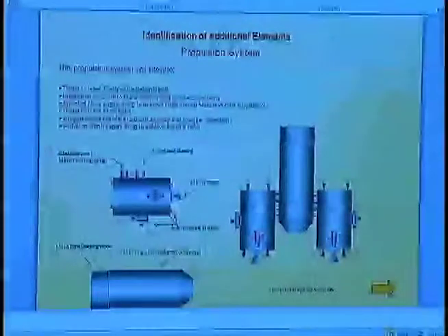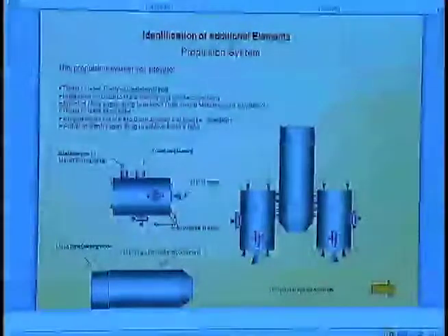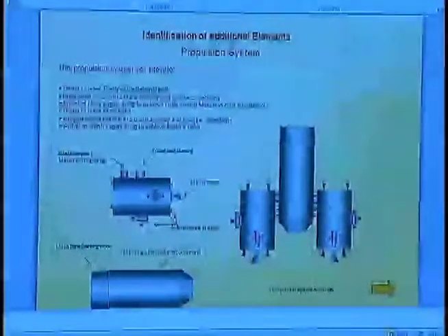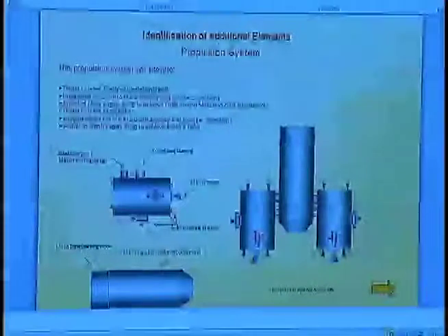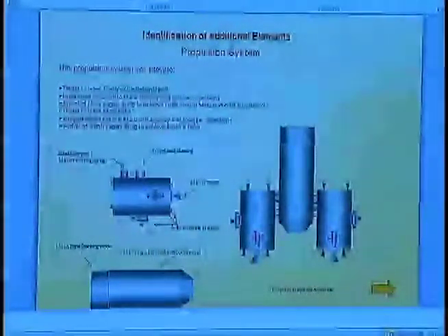Now here's the propulsion system. Let's expand on this. This system is formed by a module which contains propellant to feed two rocket systems. Each of these rocket systems has a main engine, secondary engines, and route correction engines. Inside is a propellant which is to be used by the secondary and correction engines. The main module has the computers and interfaces which are needed to control the engines.